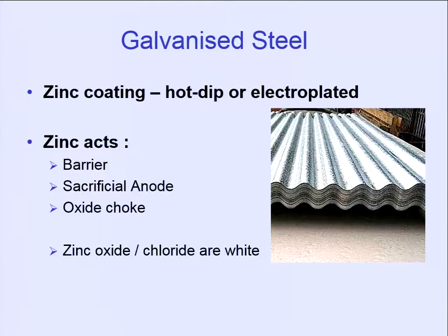And they calculate out the size of the block and the distance apart they should be, to ensure that the steel, the tube, is always at a suitable cathodic potential. So in a sense it's sacrificial anode, but scrapping the barrier stage, you're going straight to, right, the anode and cathode are exposed to the marine environment in this case.